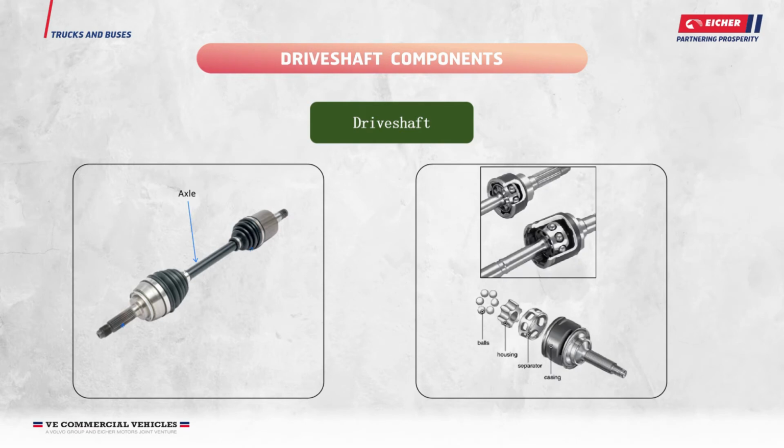The shaft consists of splined ends and constant velocity joints, or CV joints, on both sides. The inner joint is completely flexible and has the ability to move in and out. The outer joint is also flexible, but it cannot move in and out. The CV joint is designed to accommodate the change in height and transfer the same amount of torque to the drive wheels when the vehicle is moving over a rough patch.